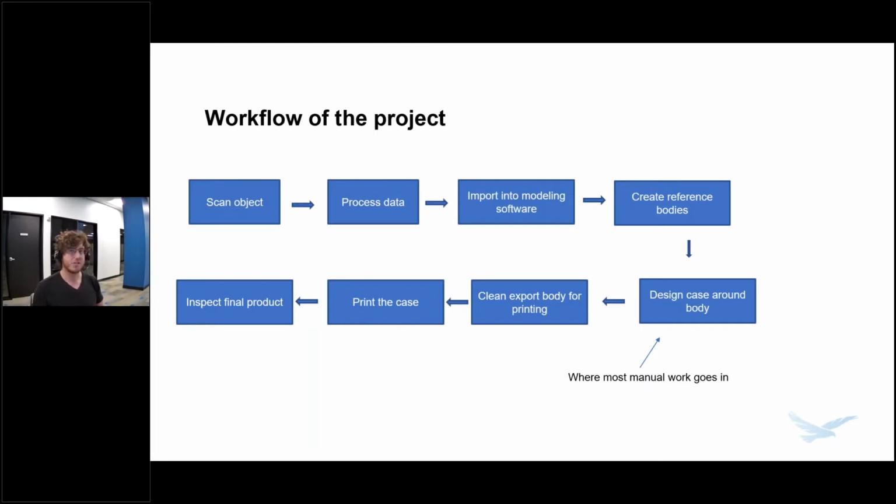Once we finish processing that data, we can get something like a mesh. Now, mesh does have some properties to it, but it is pretty graphical. It doesn't have that much actual modeling properties to it. It's not an actual solid yet. While we can do a lot with meshes now in SOLIDWORKS 2020, for example, it's still really handy to have that as an actual solid body, so we can use it with our other future parts in being able to subtract them with like Boolean operations with one another.